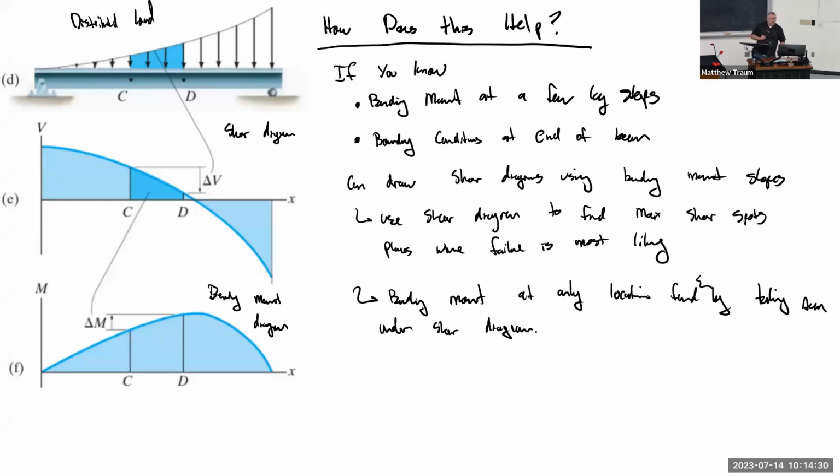Running out of time. Oh, okay. Can I say something? Yeah, please. So the shear diagram basically is just a shear force diagram. It's not for us to really find the maximum shear stress from the shear force. Now, normally in this bending situation, the normal stress caused by bending is dominant, and the shear stress, we can show some calculation later, is several orders of magnitude lower.